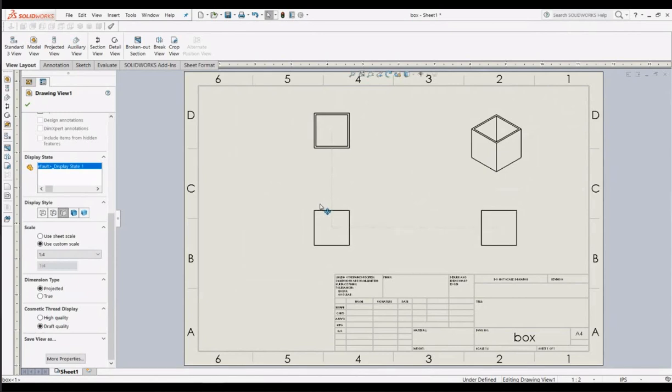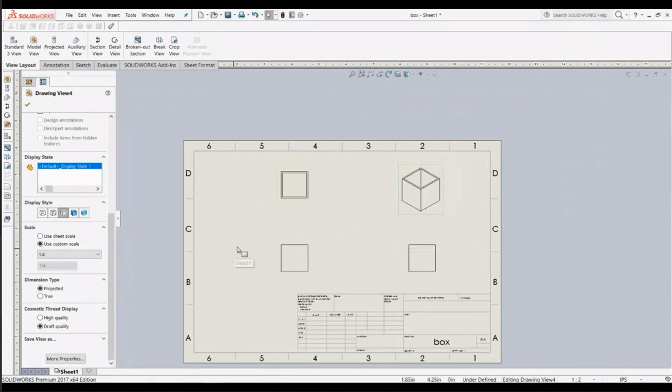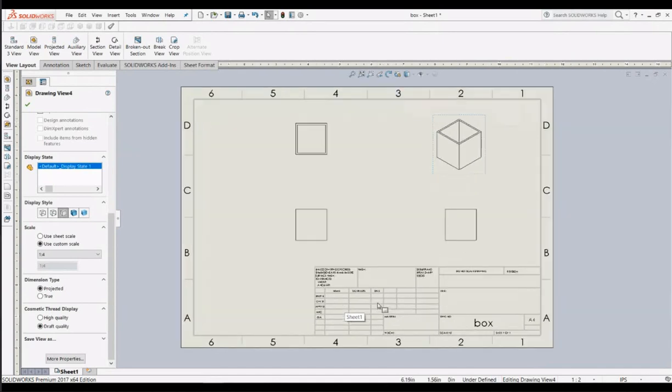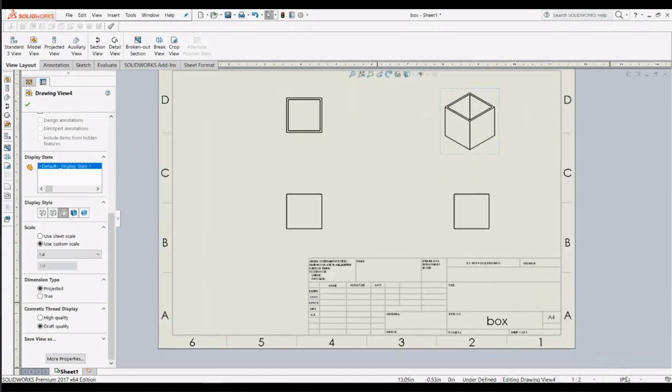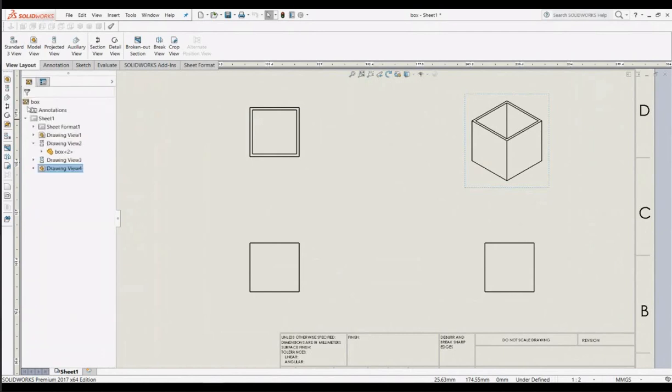So now it's going to be easy for us to assign the dimensions. Okay, before that, actually, I forgot to do something. Did you guys realize what my mistake is here? My mistake is I didn't assign the standard dimension. So I have to assign it before I did the drawing. So after I assign it, I have to go back to the annotation. I'm done with this, right? So I already scaled it into custom scale, and then I can always be okay with that. So closing the dialog. Then now I'm going to do the annotation.